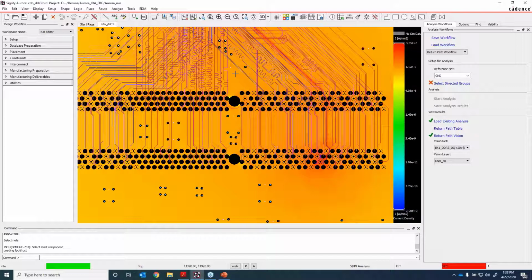Where are the parameters set up to check impedances? The parameters themselves are properties of the traces you're laying down. So the impedance it's looking at is purely the copper trace impedance. It looks at the proximity of other traces, the initial copper makeup, the width, all of those.